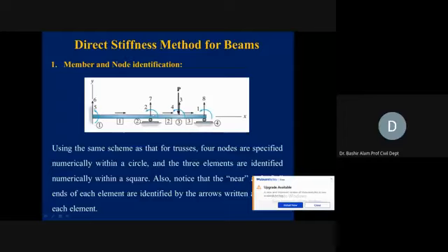So this rotation we take 1, then let's say under this 3 we take 2 and 3, 4, and then we come to the restrained one, 5, 6, 7, 8, whatever order, but free first and then followed by the restrained displacements. We have 4 joints, 2 displacements possible at each one. So this way it is becoming total 8 degrees kinematically indeterminate problem.